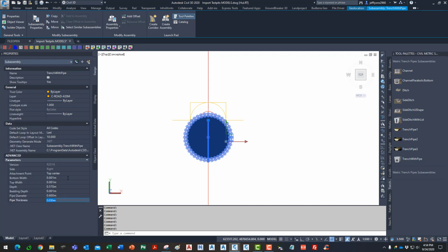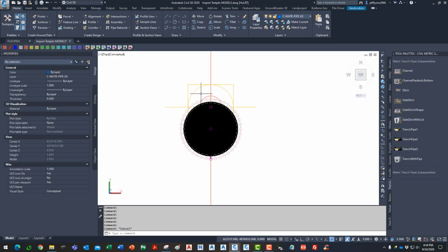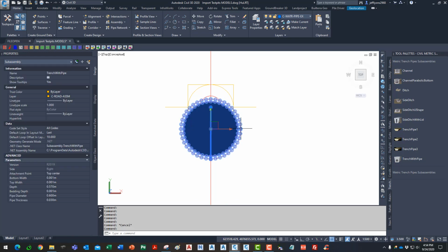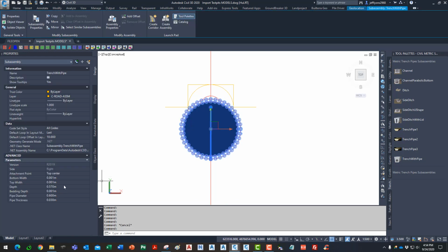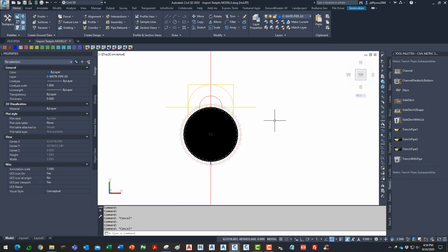And so what happens is you're building this pipe without the bedding piece. And we'll just take a real quick look at that again. I hope I didn't screw that up. So the bottom width, top width, the depth, top center, bedding 0.6. You can make it minimal, and that pipe will now show up in the model a certain way. So how are we going to do that?